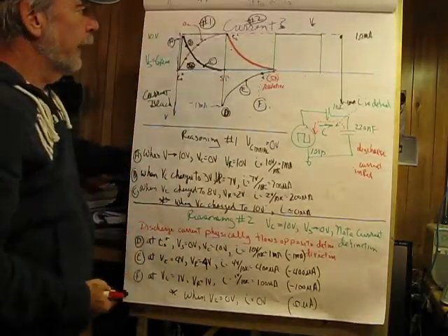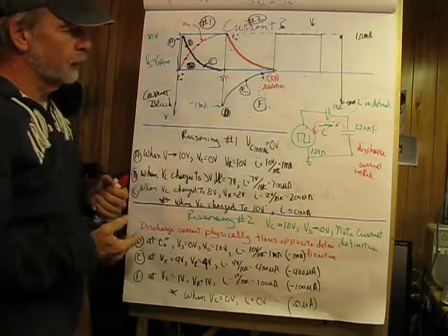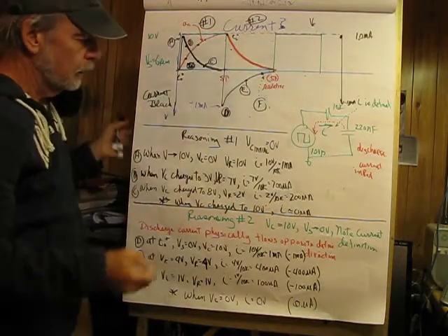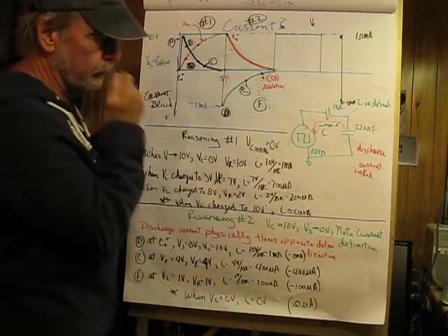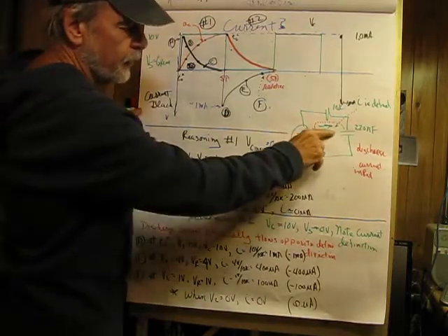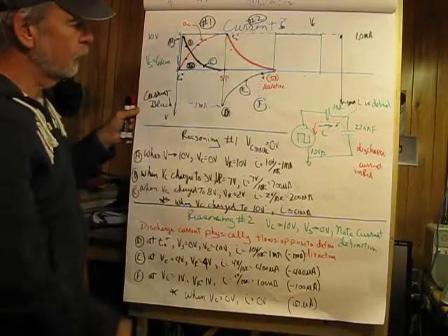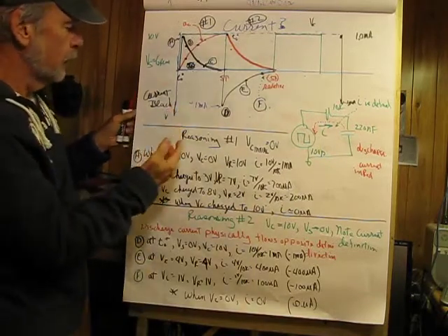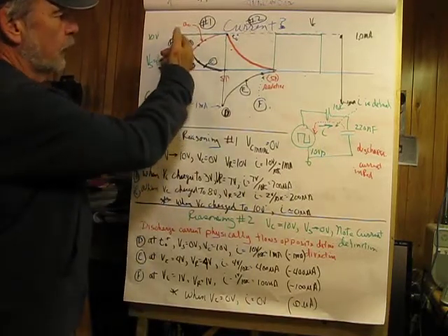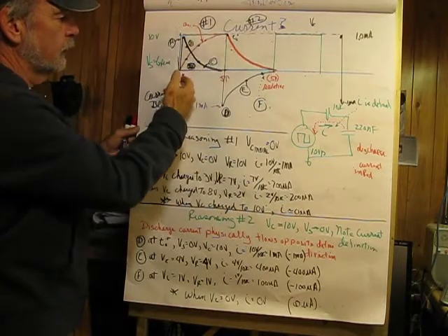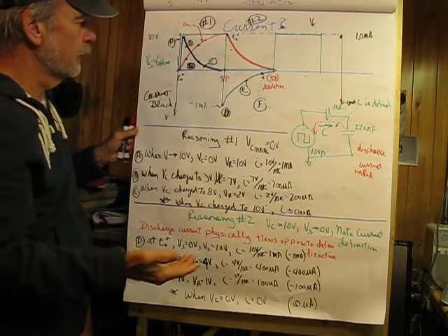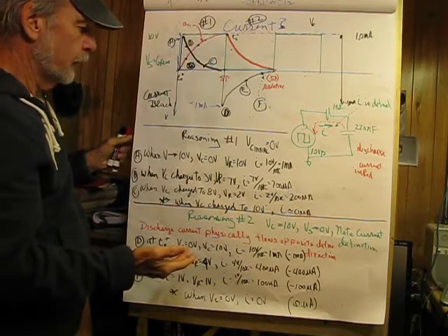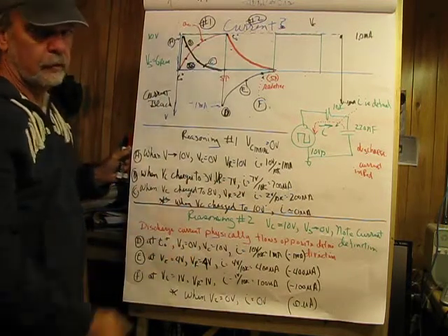And one more bad guy. I'm just going to use some examples here, so, you know, it's not bad when you take it apart. The definition of I is flowing in that direction. So let's look at the charging here. And what we see here is when our input waveform goes to 10 volts, the capacitor asymptotically approaches 10 volts like before. And now what we want to do is find out what the current looks like.